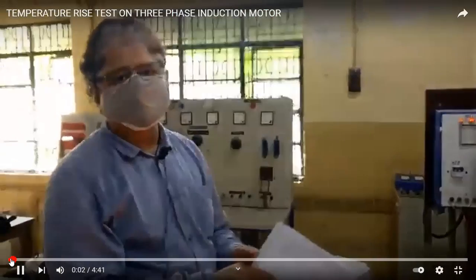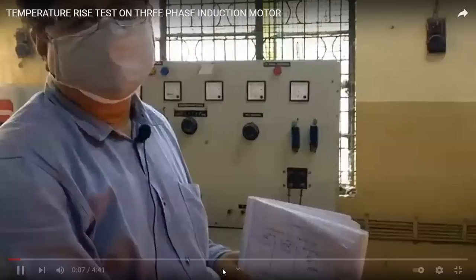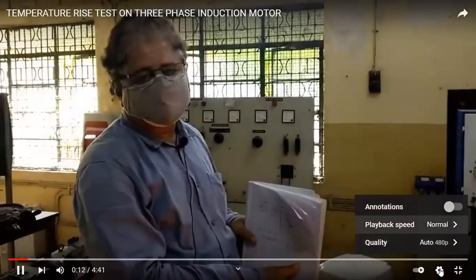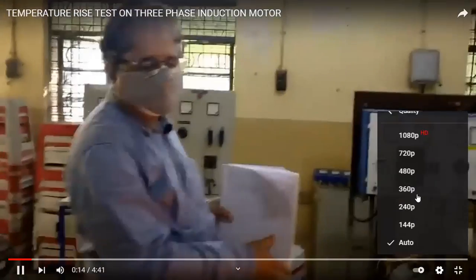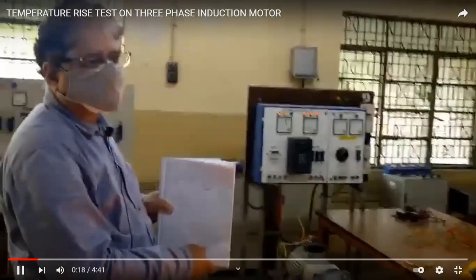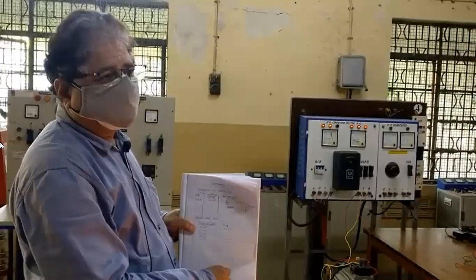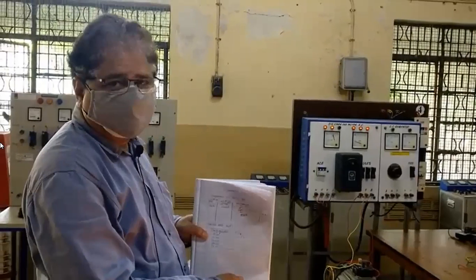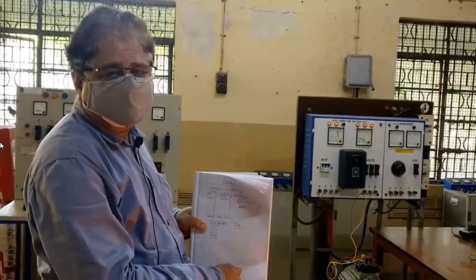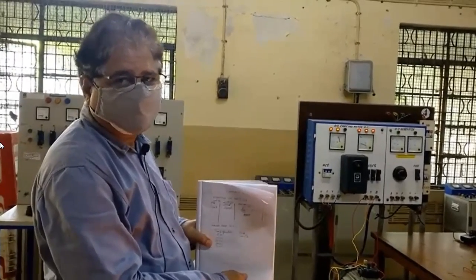This experiment is a temperature rise test on the three-phase induction motor. Here also we are going to perform a full load test on the induction motor to record its temperature rise after certain hours of operation. The temperature rise can once again be calculated using the DC resistance method, by injecting DC current into the winding after switching off the supply.